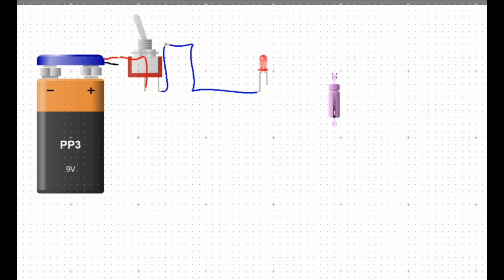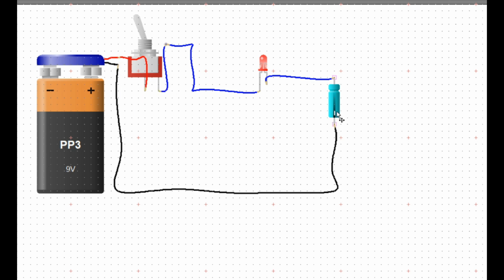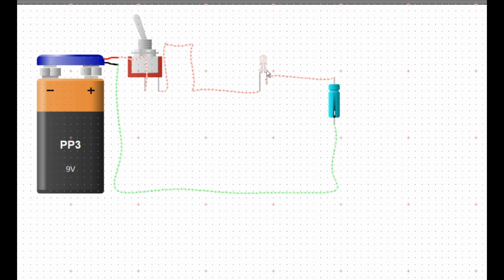2. When you first connect the circuit, the capacitor charges up quickly, allowing a brief current flow. 3. Once the capacitor is fully charged, it acts like an open circuit, a break in the circuit stopping the current flow. 4. Without current, the LED doesn't receive power and doesn't glow. In a DC circuit, a capacitor behaves like an open circuit after it's charged, preventing current from flowing through the LED.